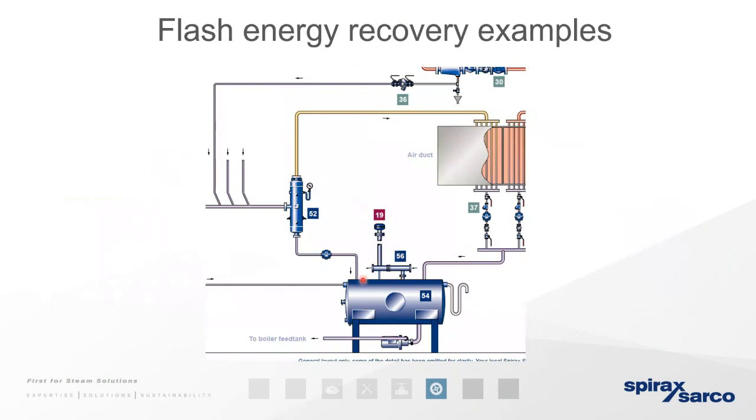So here we have what we call an exhaust vapor condenser, which we install on our condensate recovery systems, and there we have water running through it, or any other secondary medium of heating. As we now enter this condensate, where the flash would have gone to normal atmospheric pressure venting, we now run it through what is almost like a shell and tube heat exchanger. We run the secondary water through it, recovering that energy, and we reduce that loss of flash steam to atmosphere. And that is how we recover the flash steam from a mechanical condensate recovery pump. Great question. Thank you.